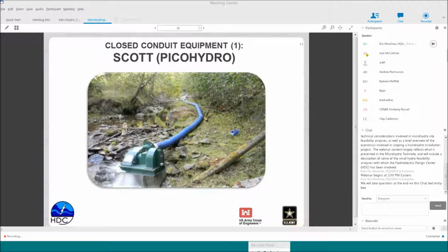What we don't see in this picture is up here. There's a small dam or weir that's causing this creek to pool. And some flow is redirected, and instead of flowing down the stream, it's being routed through the hose here. And this small microhydro scale turbine is set up so the turbine runner is on the left side of the housing here, and then there's a generator on the right side of the housing. And that small 5 or 10 kilowatts of electrical power is fed out through the line here.